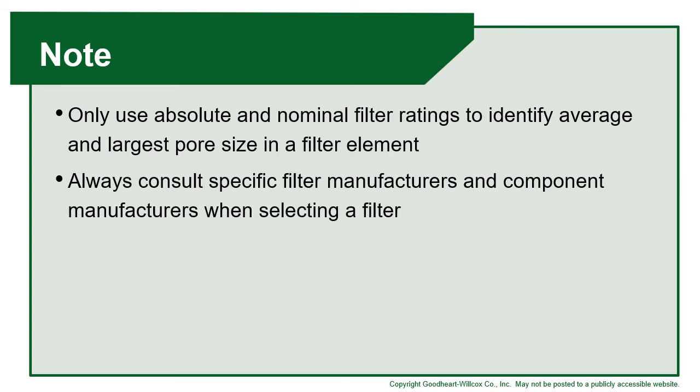Keep in mind, just like all the other components we have worked with, it's important to look at all the details provided by the manufacturers. They have data sheets just like they have with other equipment, and you want to make sure you pick a filter that meets your needs. So definitely know the difference between absolute and nominal filtration rating, and of course consult your data sheets when selecting a filter.